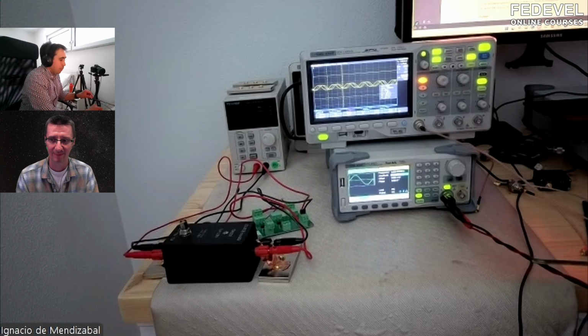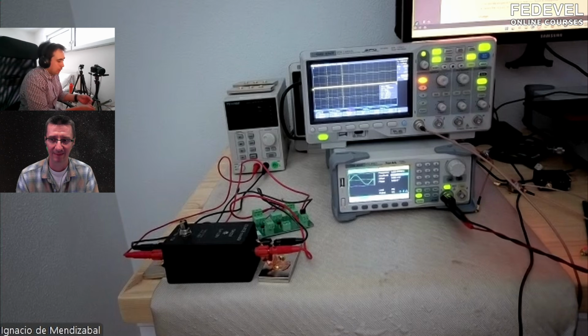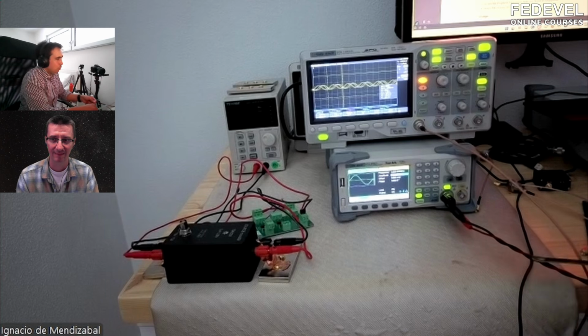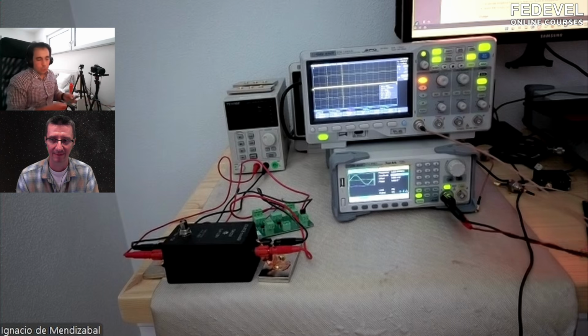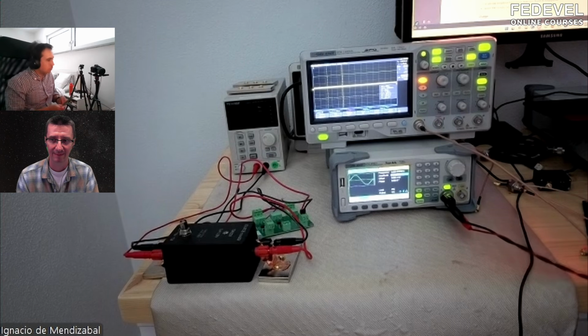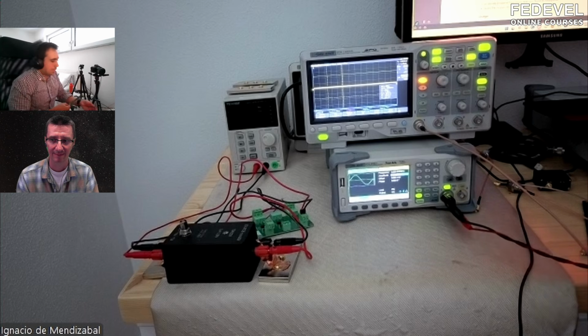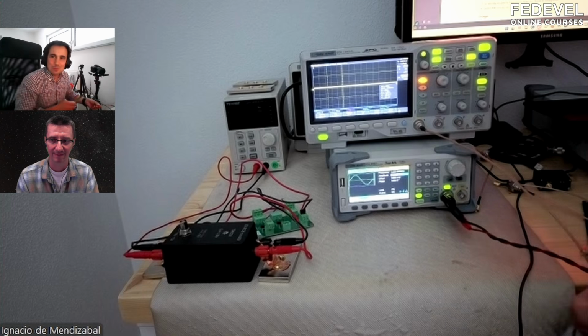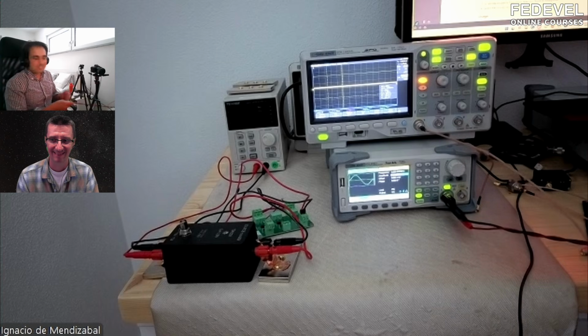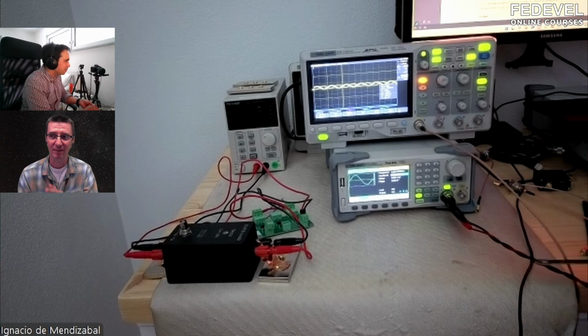What happens is that in reality the twisting is never perfect, so you need to be very careful on how you twist, the distances and the installation. It reduces the amount of field, so it's always a good technique, but you always need to see if it really makes sense to twist all your cables or if it's going to bring you more pain.